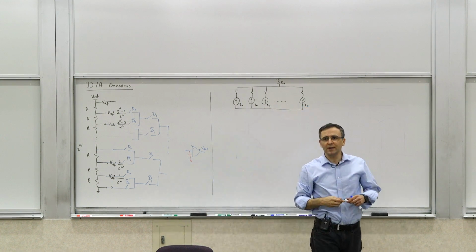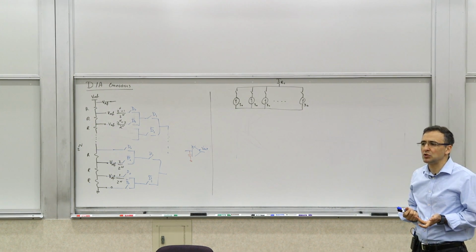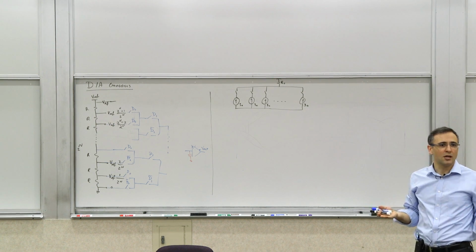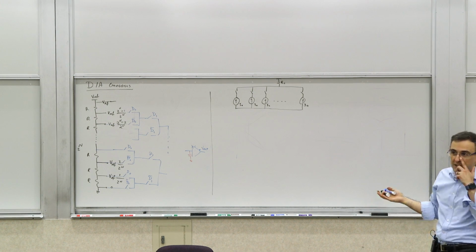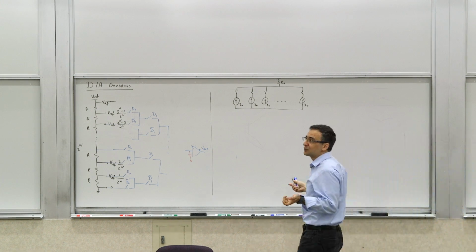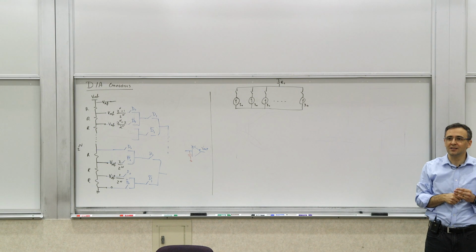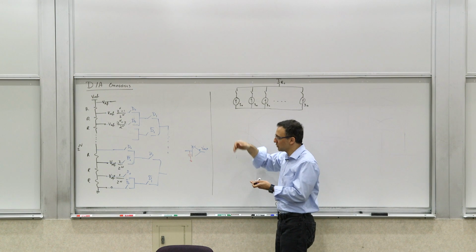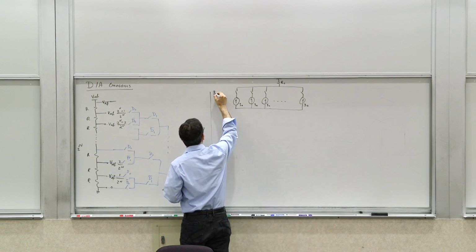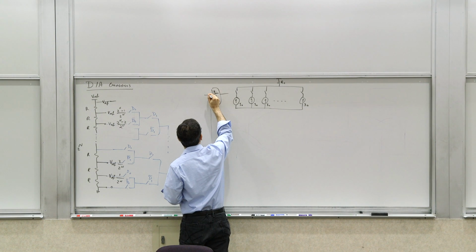So is there a certain kind of code that we can apply to those switches for this to act as a D2A? Thermometer code, right? I mean, we can basically just turn the sufficient number of switches on, right? So, if you need an 8-bit D2A, what you need to make is 256 current, or 255 really, current sources, right? 2 to the n minus 1. You need to have some sort of a binary to thermometer converter, which is a simple combinatorial logic circuit.